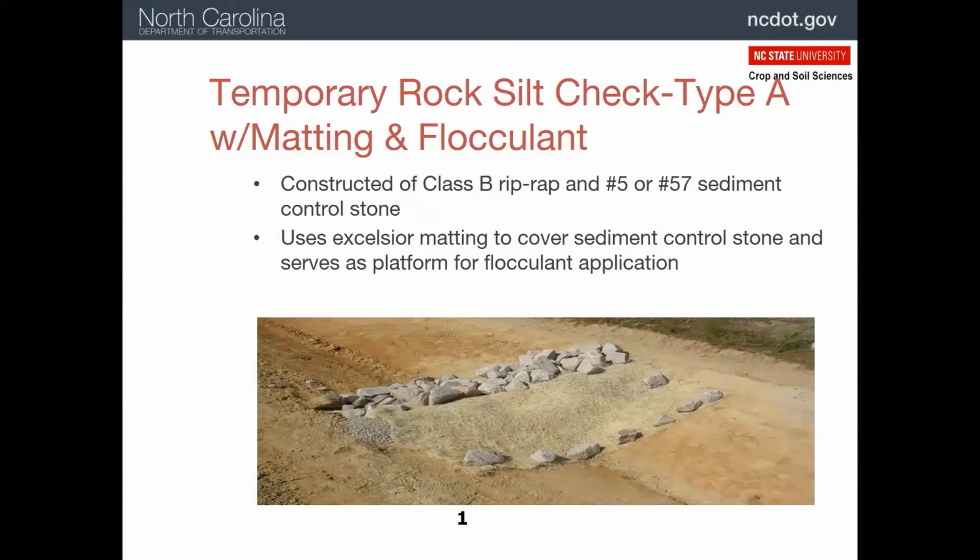Does anybody see anything wrong with this check dam? If we were in class, I'd hope to see a lot of hands. Notice how it's flat. It should not be flat. This should be a low point right here. Maybe a little bit low, but it's not very low. It needs to be pretty clear.